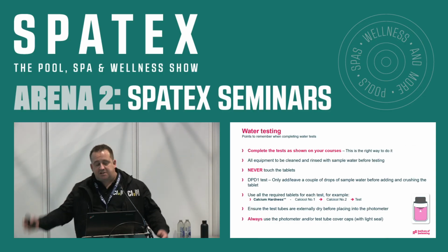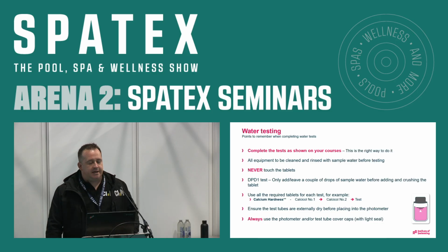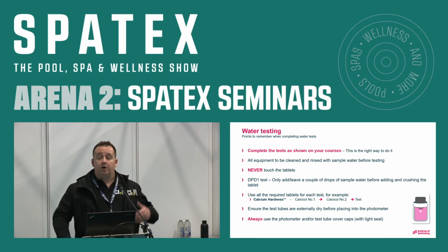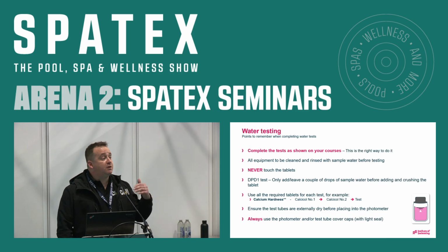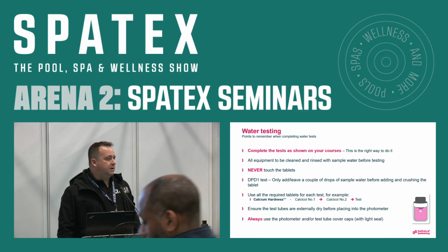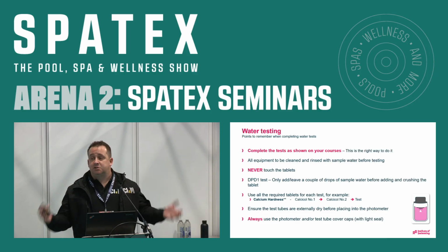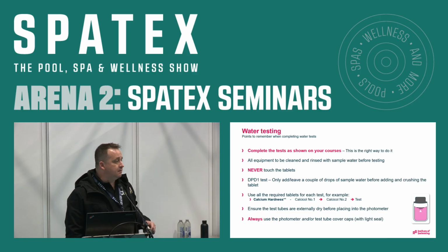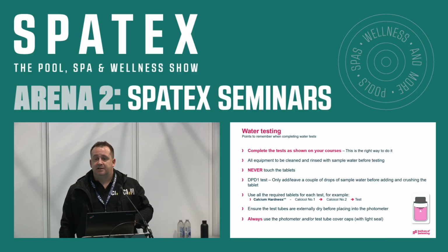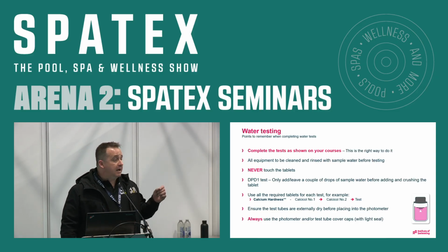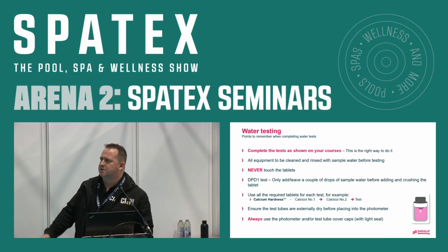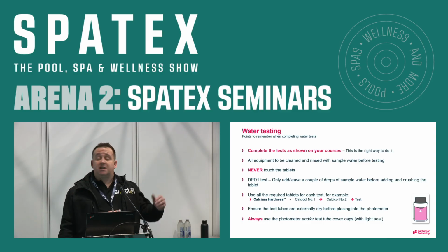Okay, so points to note when looking at water testing. Complete the test as shown to you, as taught on courses, or in the instruction manual. Make sure you follow the right ways of doing it. Make sure your equipment's clean. When I teach courses, I have a few little crushing rods that I've collected from sites over the years that are black. It's just biofilm build up, and it's contaminating every single test you do. Right old mess. Okay, never touch the tablets.